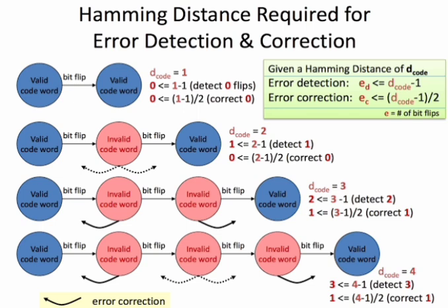We can also form the Hamming code by changing the places of b0, b1, b2 and m0, m1, m2, m3. For example, b0 plus m0 plus m1 plus m2 equal to 0. b1 plus m0 plus m1 plus m3 equal to 0. b2 plus m0 plus m2 plus m3 equal to 0. So b0 equal to m0 plus m1 plus m2, meaning XOR. b1 equal to m0 plus m1 plus m3, b2 equal to m0 plus m2 plus m3.